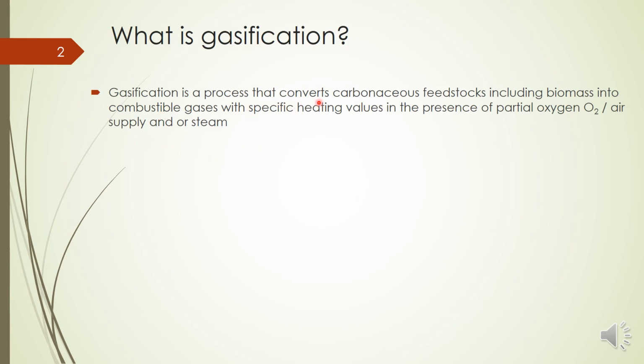So gasification is a process which converts a carbonaceous feedstock including biomass into combustible gas. So mainly we are converting a solid biomass into a gas, a mixture of gas which is very easily combustible, so that we can use it later or for other applications if required. And remember, this gasification can be done to any solid carbonaceous material, not only biomass, even coal. Coal gasification is another important application of gasification.